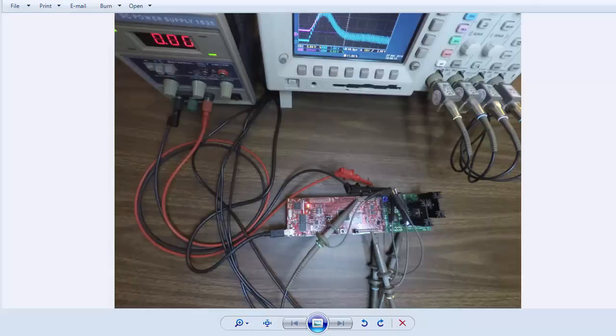In this case study, a buck power supply development kit is used as a platform for an example buck converter. A bench supply provides bulk power to the kit at 9.2 volts with a 3 amp current limit. The buck supply regulates the output at 2.0 volts into a test load.